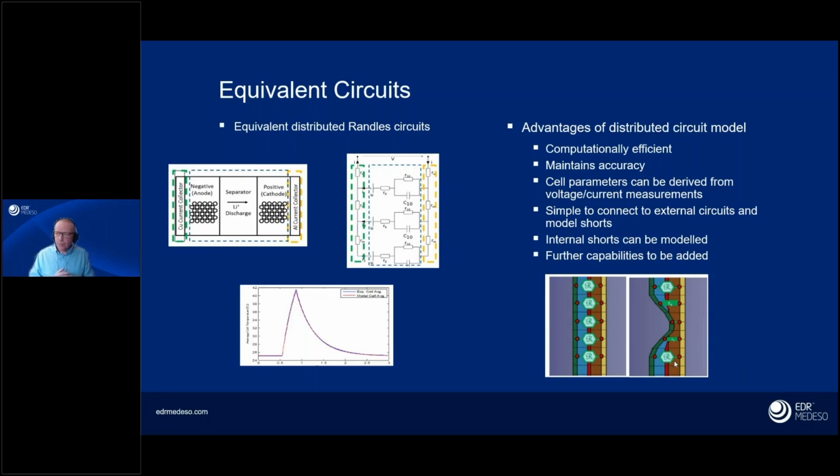You can see on that bottom right, once we've deformed those outer collector layers sufficiently, we can penetrate through the middle separator, and then potentially those conductors can contact, can't they? We'll get a thermal short, which will lead to increased temperature, which can ultimately lead to some fairly catastrophic events, but we can simulate that now.